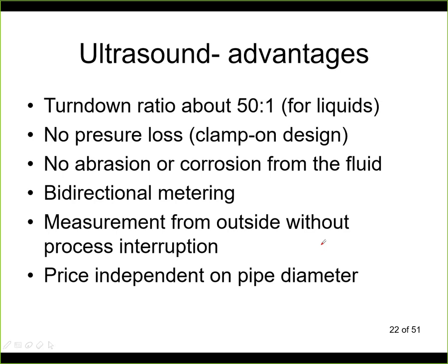For the clamp-on design, we do not have any pressure loss at all, and we don't have any abrasion or corrosion from the fluid, because it's separated by the wall of the pipe. Now the Orifice plate was used only for one direction, but the ultrasonic can measure in both directions, so the flow may go from left to the right, from right to the left, and no problems.